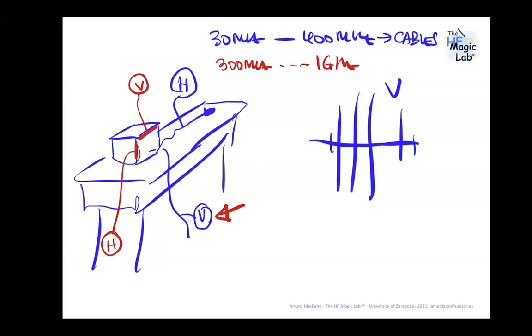If you work with near field probes, you will be able to identify what part of your system is the good antenna. This is one important thing, to identify where the antenna is, so you can try to minimize its effect. If the case is plastic, probably you can radiate at higher frequencies with the PCB if you don't have a good layout. Many possibilities.